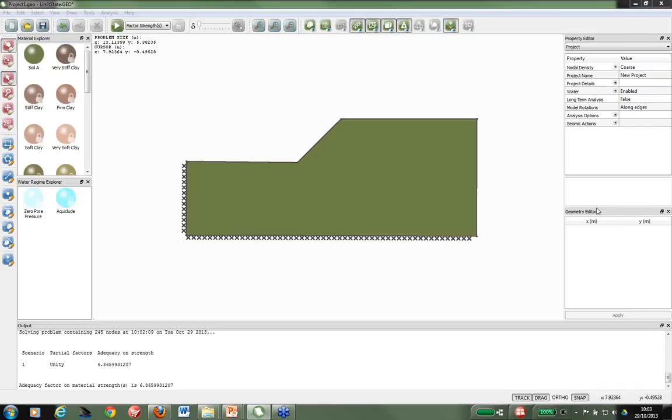Okay, a question about, can we model a problem where the soil is potentially affected by preload in anchors? Again, I think this comes back to plasticity analysis. That's the kind of initial condition. So at plastic collapse, a preload should not have an effect on the collapse. You could look at preload in advance if you wanted to see if it would cause your anchors or whatever to move, but if they don't move, then that effectively is an initial condition which should not be affected in a purely plastic analysis.